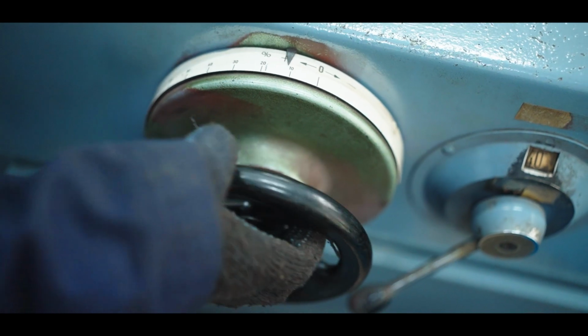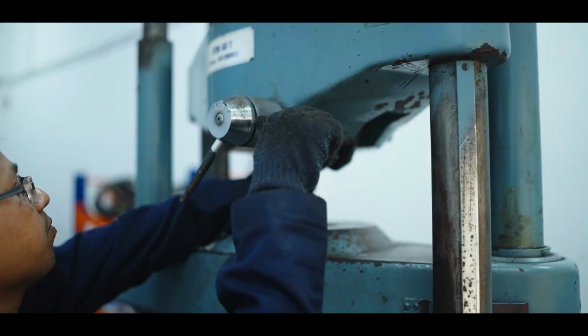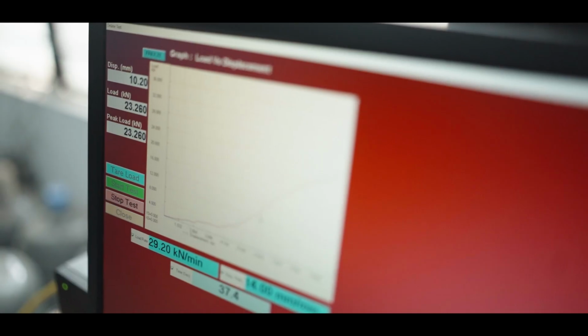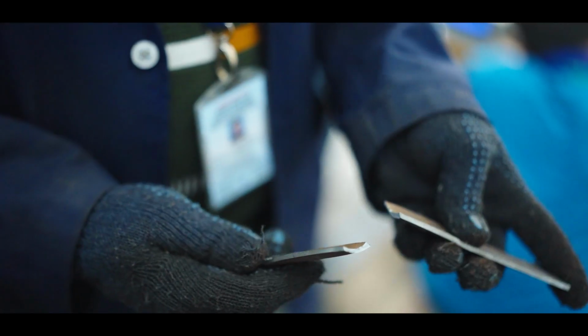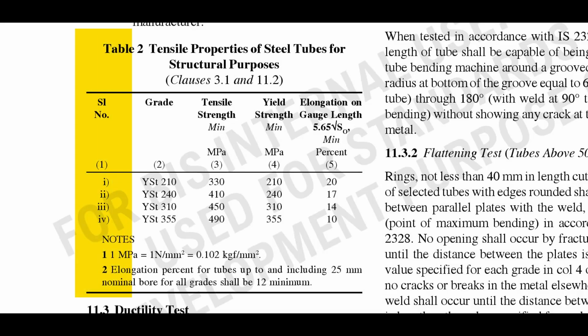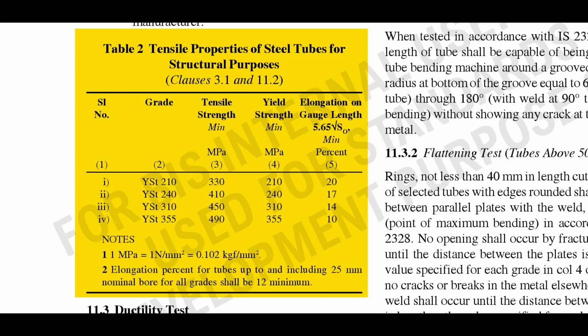As the load increases, the sample will eventually break under stress, and the software will automatically display the tensile strength of the sample. The requirement of the tensile strength for various grades is as per Table 2 of IS 1161.